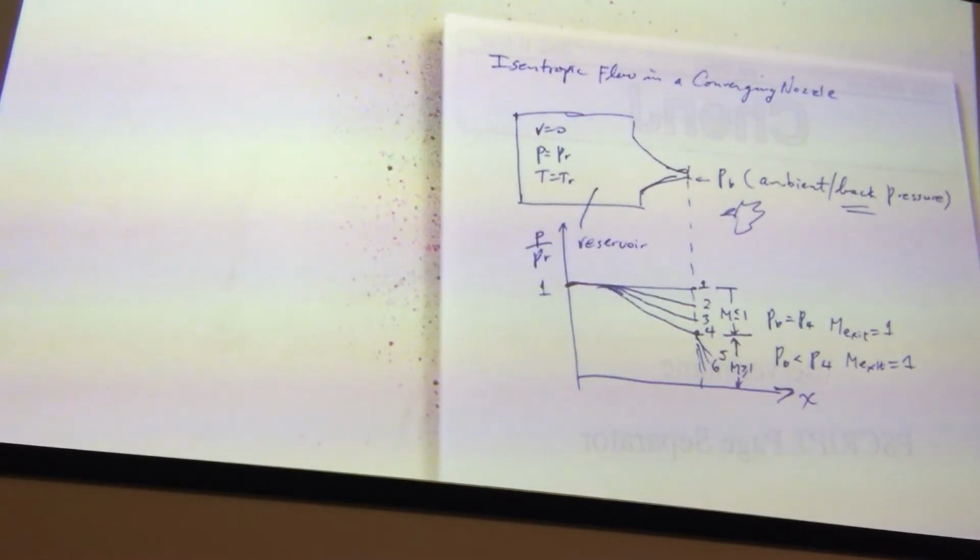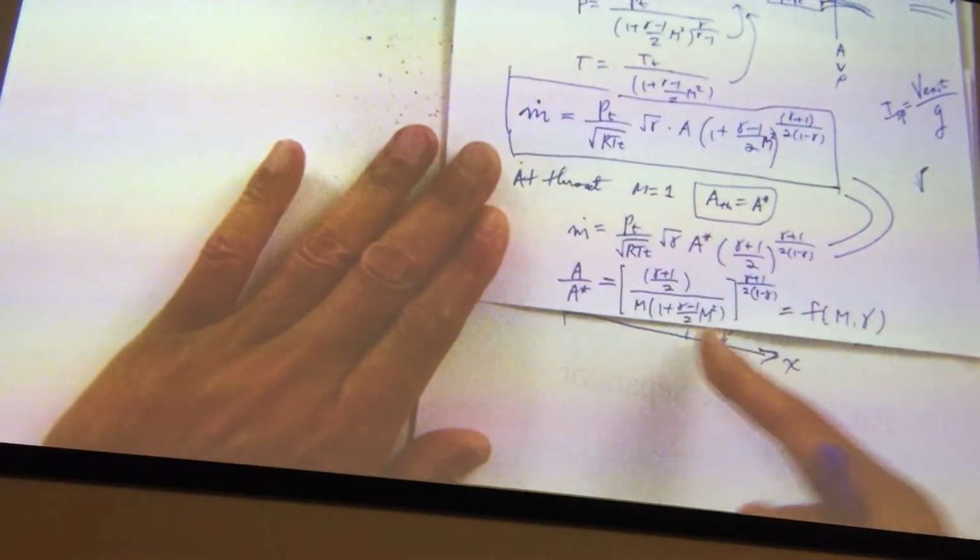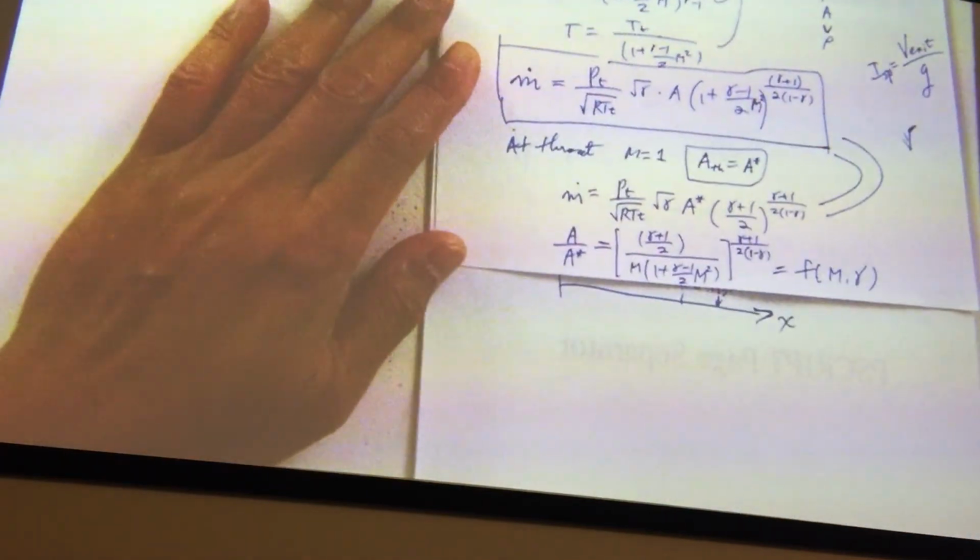So if the upstream gas couldn't feel any further change or any further lowering of the back pressure, this profile will change. It changes from here to here to here. That's all possible because Mach number is less than 1. Okay? But once you go down to a certain level, it will not change anymore. Right? So by that time, M should be equal to 1.